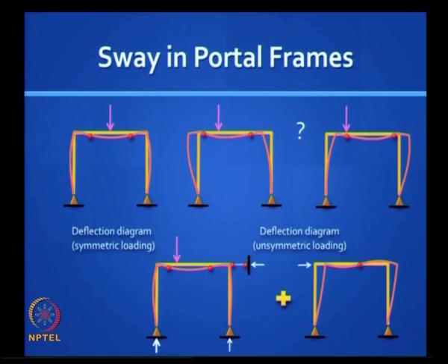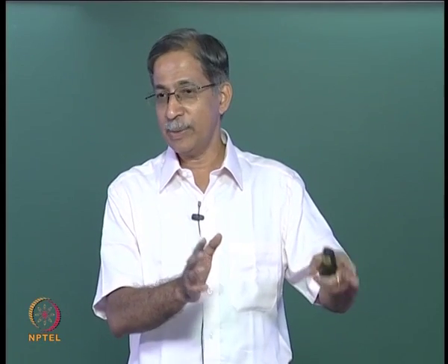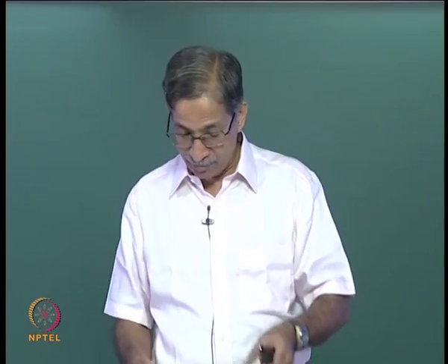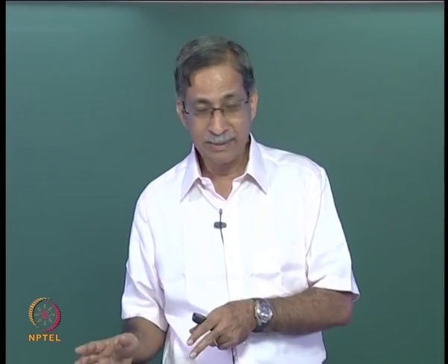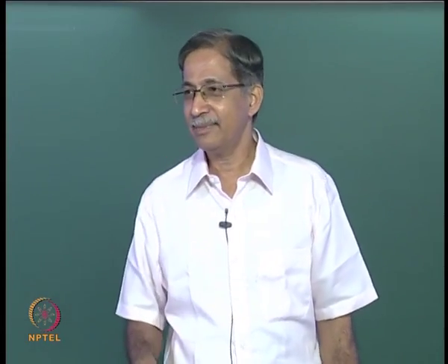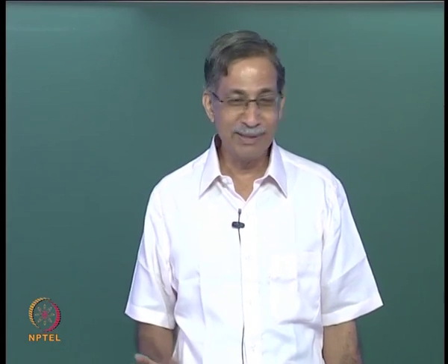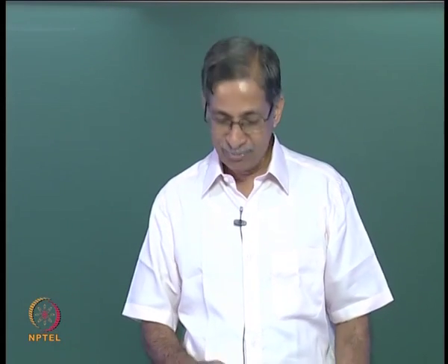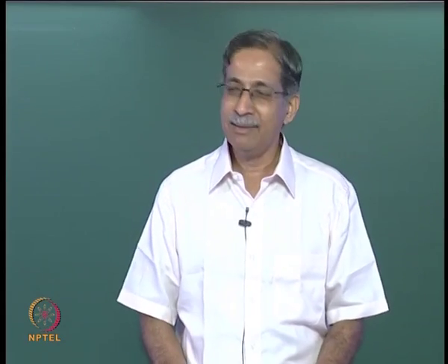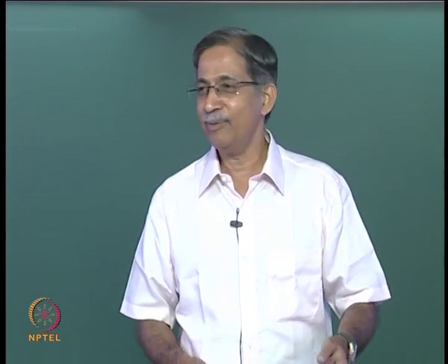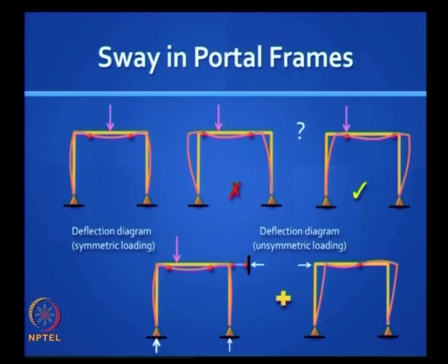you have to do another analysis which is called a pure sway analysis, where you have a horizontal load acting. So this is the problem with the moment distribution method, that is you need to do two distributions, one with the sway arrested, in the other you have to figure out how much that sway is, then do that analysis. So it is not worth it, and so we will not follow the moment distribution method beyond this point. We will say if you have such problems you can do it, but we have grown up and we do not do it that way, okay.